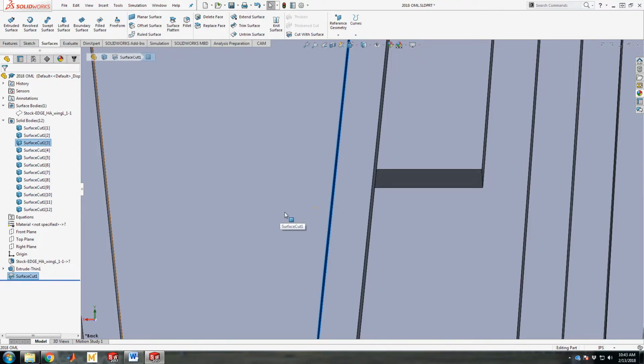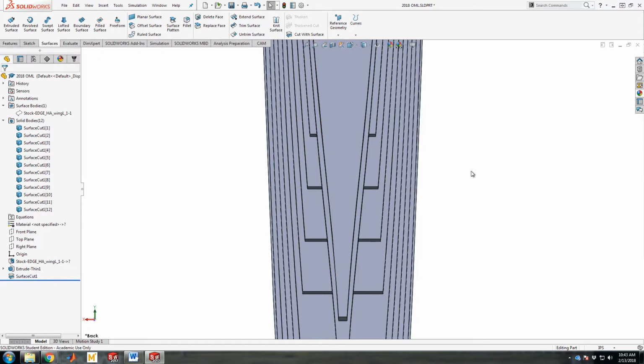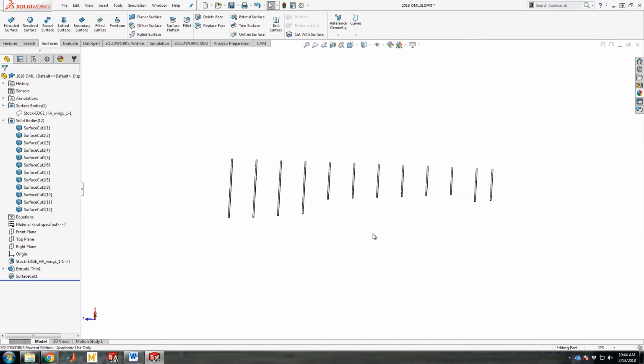The laser cutter is not going to do that for you. You're going to have to pick, probably I would say, the smaller side to put into the DXF because it'll be more compliant with the actual OML. So just be aware of that. You are being more precise than the actual ribs in the end will be.